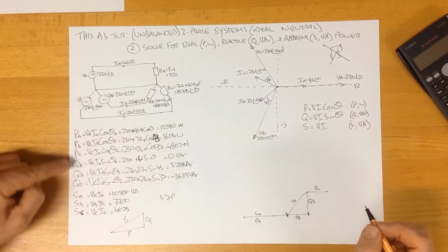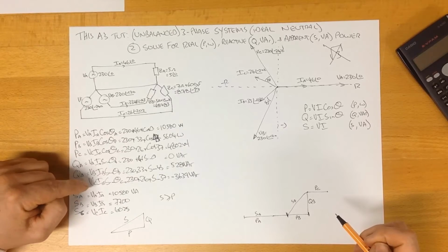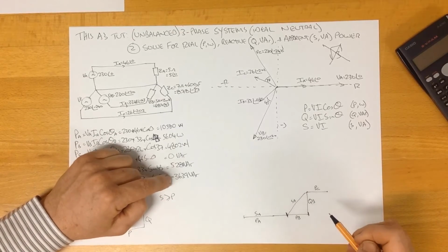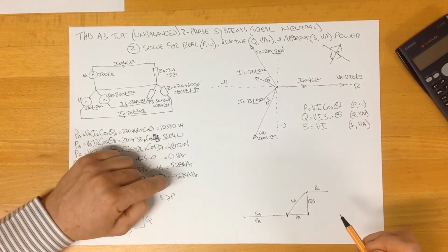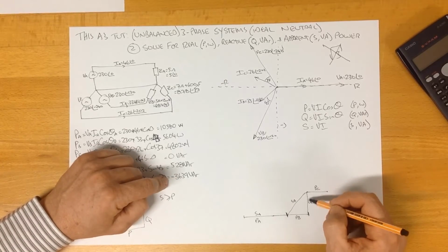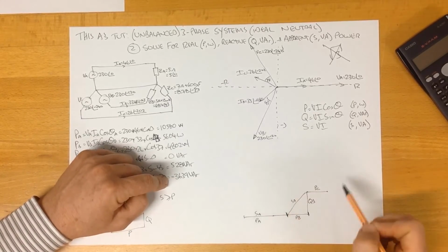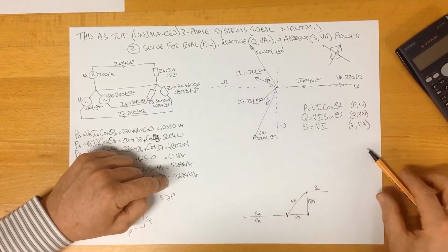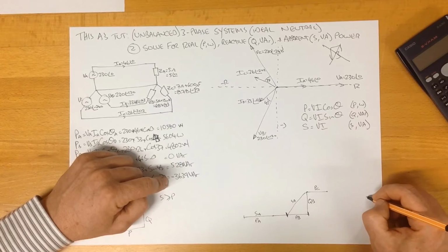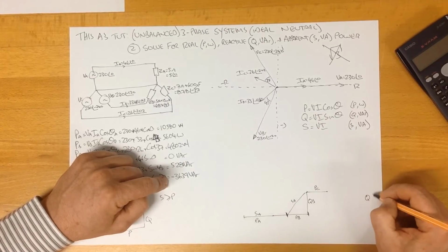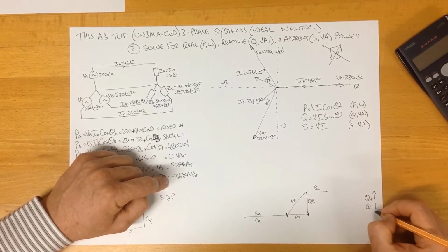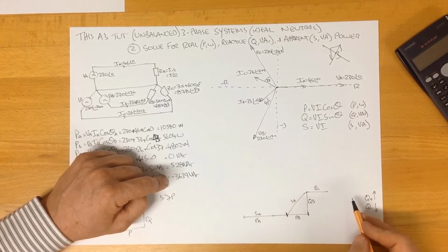And we can see here that the reactive power in phase C was 3,600, but it's in the negative direction because it's capacitance. It's in the opposite direction of inductance. Now, it's probably opportune to say you will often see in some books these drawn this way, where the reactive component Q positive goes that way, and Q negative is drawn down this way, which is the way that I'm drawing it.